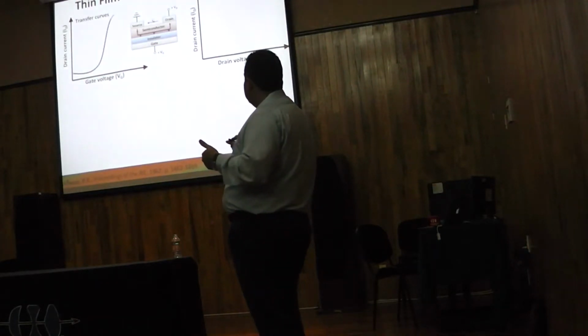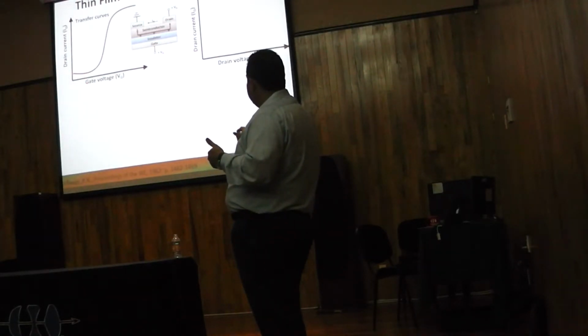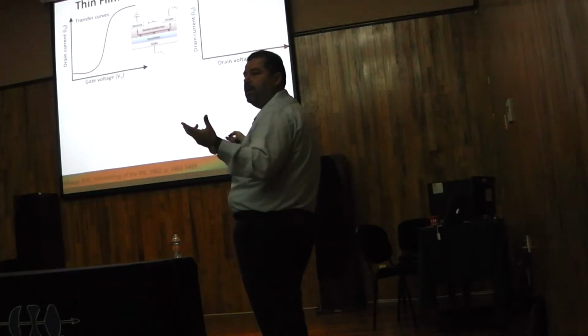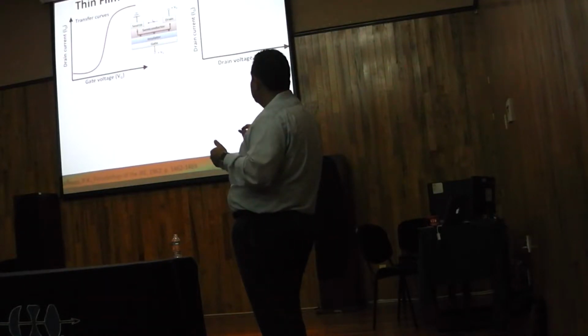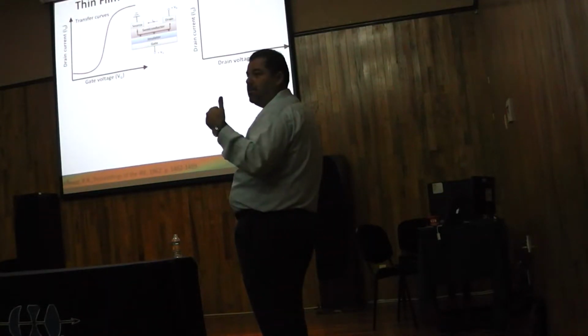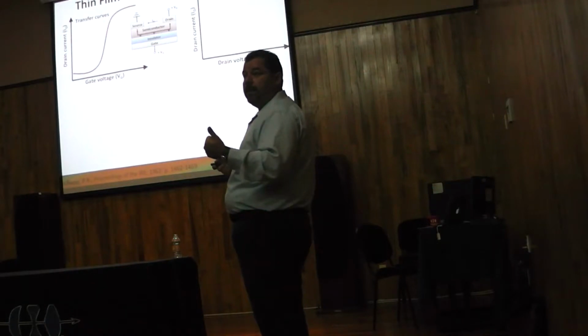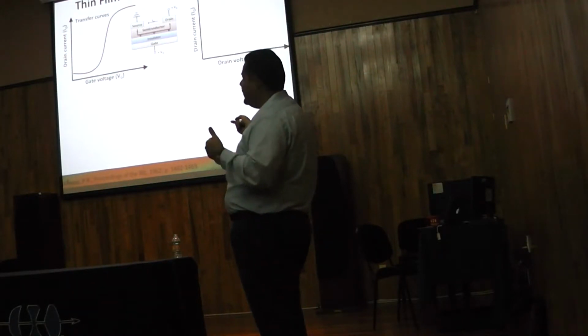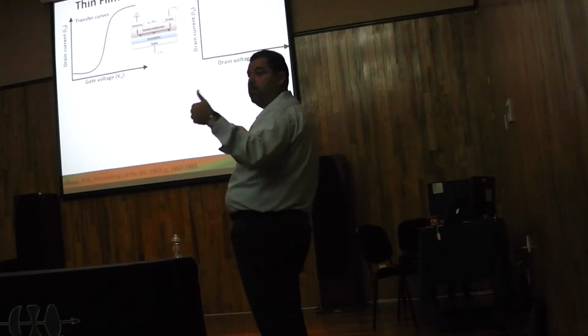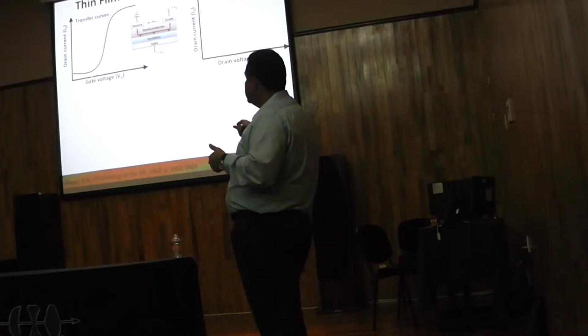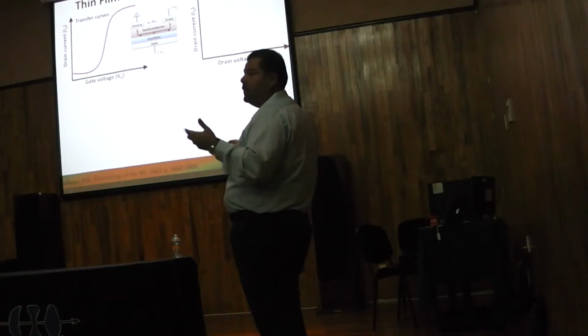And how does that look? Basically I'm increasing the gate voltage here. Whenever I see the drain current increasing, that means that I'm accumulating electrons in there. So my transistor is on. From this plot, I can extract carrier mobility and VT. The VT is the threshold voltage, which is the voltage at which the transistor turns on. From the saturation current, I can extract the mobility.